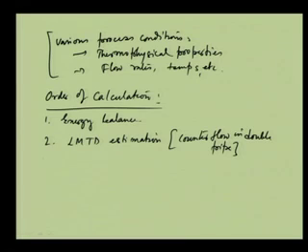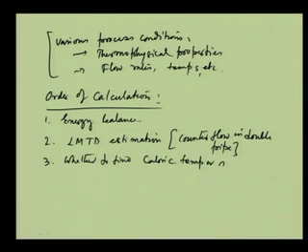And then there is another point, the caloric temperature: whether we have to find out the caloric temperature or not, to be decided based on delta T and the viscosity range, the nature of the fluid.